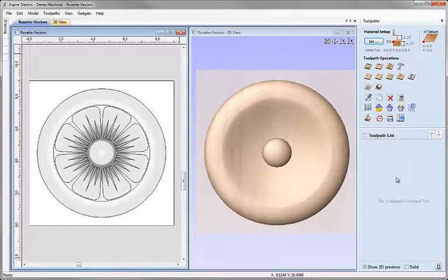As with any job where we're calculating toolpaths within the demonstration, if you're planning to cut it, you need to make sure that the values you choose for the material setup and for all the toolpaths and tooling are appropriate to your CNC, the material you're planning to use and the tools you have available.